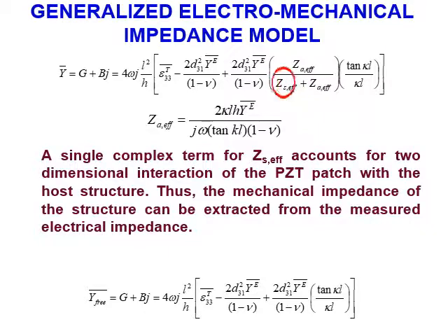To make further investigations, let us obtain the free piezo signatures, because one of our doubts is that possibly the parameters of the piezo patches are not correctly obtained here as inputs. First of all, we use this equation to obtain the free piezo signatures. How do we use it? All we have to do is set this term as 0. That is, the PZT patch is free. It does not have any resistance from the structure, so this part is 0. So we get this simplified equation for the free piezo patch.